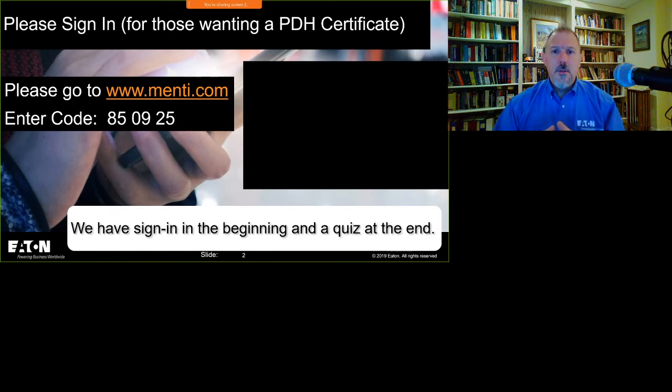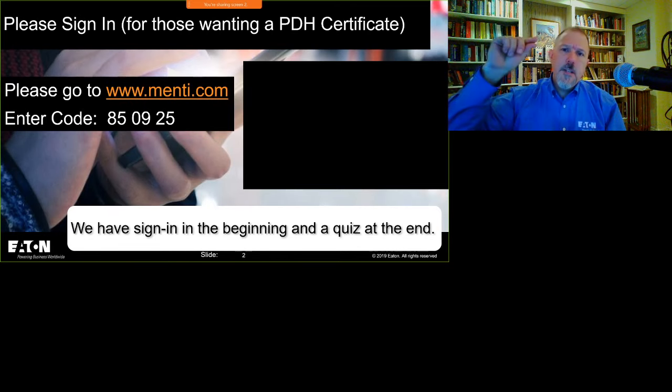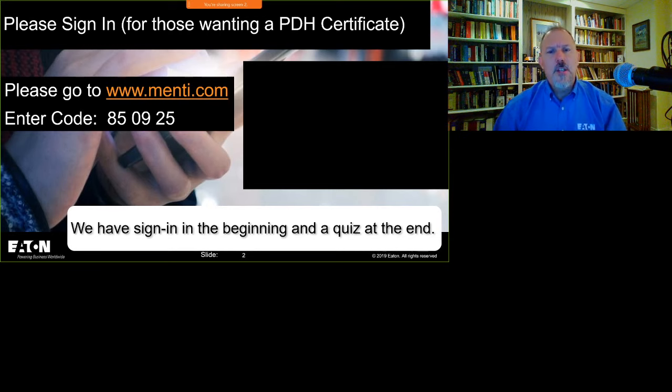rise. What they do in a heat rise test is you put the circuit breaker in your enclosure, you put temperature probes in different locations on that circuit breaker, and you run current through it. You go through a defined process in UL 489. You can't exceed a certain heat rise within that box. It impacts a lot of different things with regard to the proper operation of the device and whatnot. So you're not allowed to exceed that temperature rise, and 75 degrees C is that number that we have for a lot of different pieces of equipment.